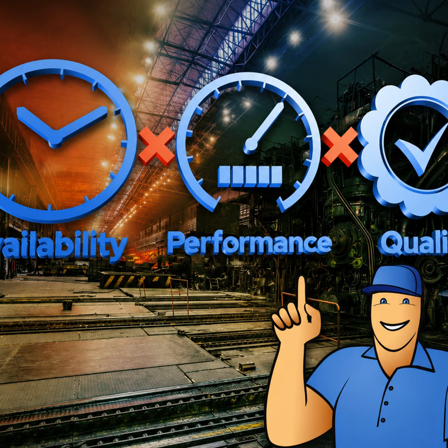After working years in processing machine maintenance, I can tell you for a fact that the leading cause of equipment failure is inadequate preventive maintenance. And some companies think they can't afford to schedule downtime for preventive maintenance. Those are the companies that spend even more time and money on emergency repairs that could have been avoided. Setup and adjustment are, to some extent, built-in time stealers. There's no way around them. For example, a tooling change on a CNC machine takes time, as does changing dies on a stamping press. But using the same strategies used in increasing capacity utilization, you can cut that time down.